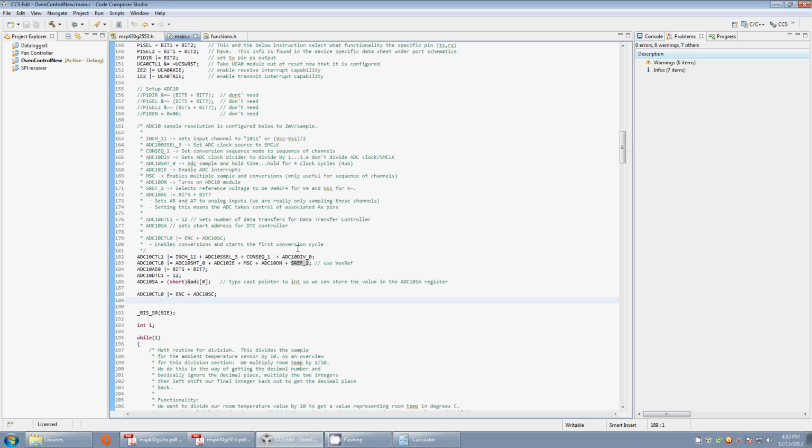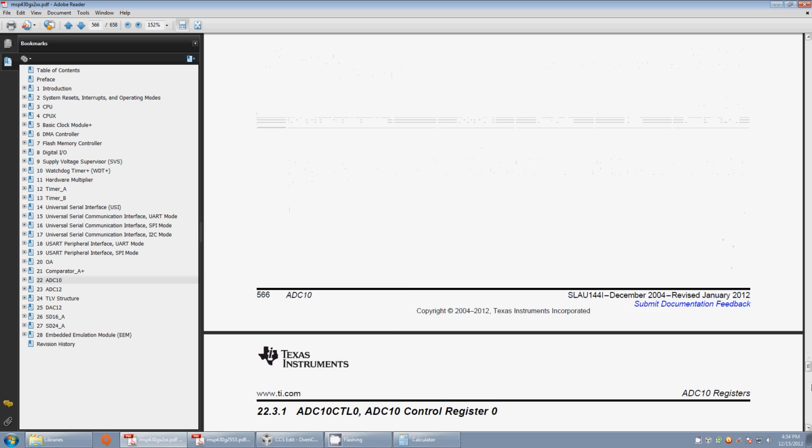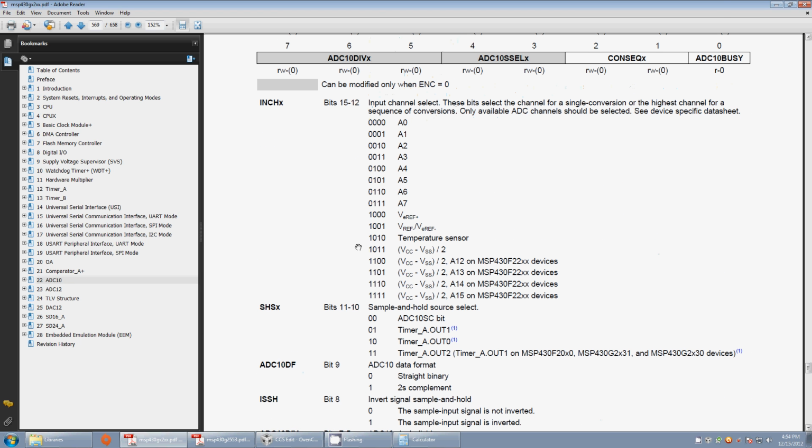So for example, what we do is we have 12 channels. If you look back at the data for ADC10, we start here at basically VCC over 2. We've got 1, 2, 3, 4, 5, 6, 7, 8, 9, 10, 11, 12. So we need a 12-byte array.